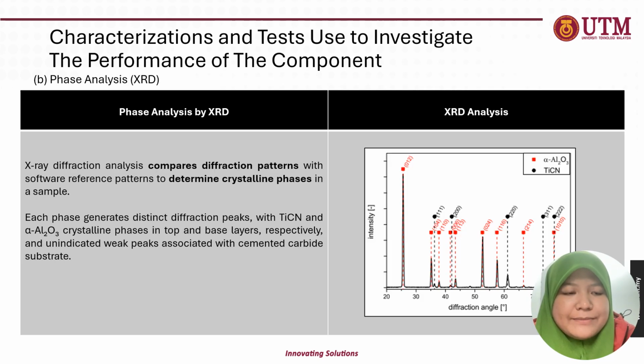The next method is phase analysis by XRD, or X-ray diffraction. XRD compares the diffraction patterns of a sample with software reference patterns to determine crystalline phases.